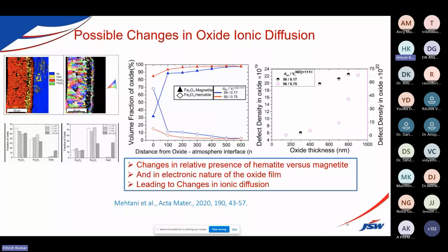Then we tried to find out, if we put it at a temperature of 500, how much Fe2O3 converts into Fe3O4 for 5 minutes, then 10 minutes, and 15 minutes, and how that fraction changes, or at 200 degrees or 300 degrees. So that type of work we did. To do that, we make it in the form of a pellet.